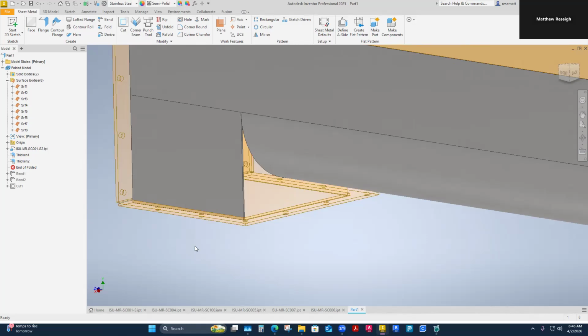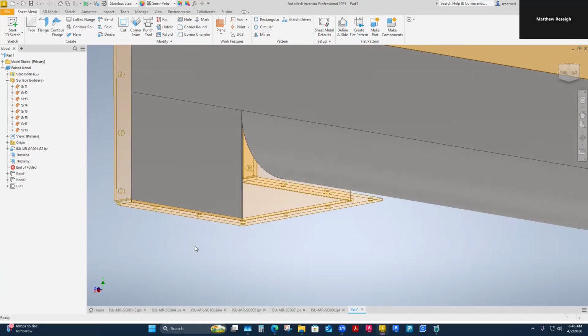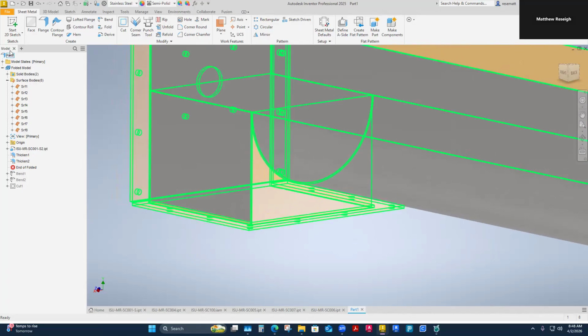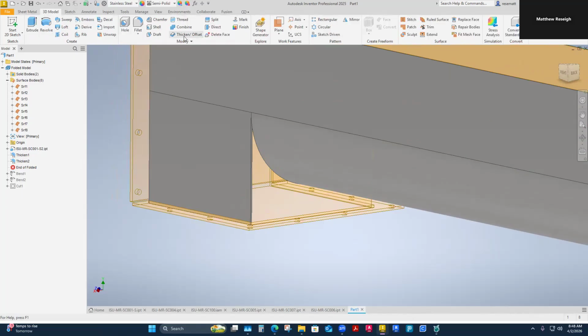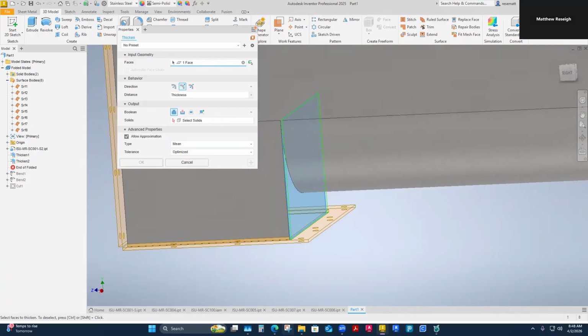But what I want to do now is thicken the next as a different solid itself. So this is just another way to approach this. It's like I didn't love how that way was coming out. So can I come up with another method to do the same thing and get to the same results, but maybe get better bends where those two meet? So that's my process here. I'm going to say, well, let me try this. I'm just going to thicken one side, and then I'm going to come in here and thicken the other side independently. So this is this side now being thickened independently.